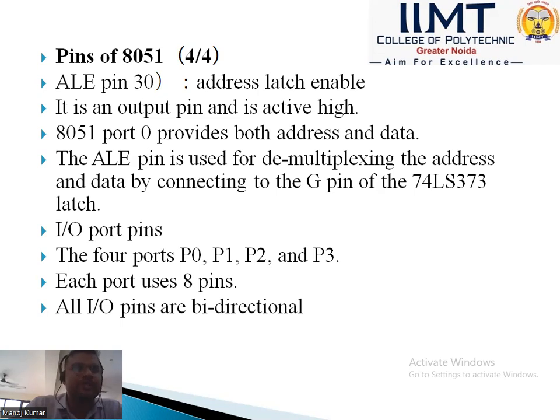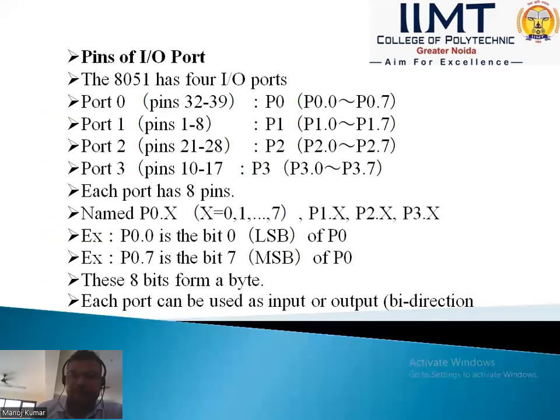Input-output ports: the four ports P0, P1, P2, and P3. Each port uses 8 pins. All input-output pins are bidirectional. Bidirectional means it can work as input and output, and again from output to input. This is called bidirectional.